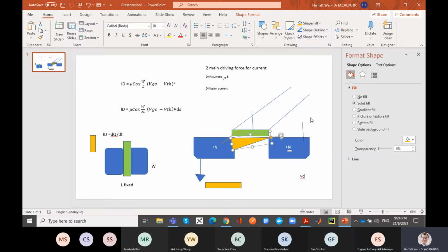Yes. So I start increasing this because I want to keep pulling more and more. But as I increase this, I'm reducing the voltage difference between these two, which means very close to this part here, there's not that much attractive force to pull out electrons, correct? Yeah. But there's still a great electric force here because this is Vg and this is 0 volts. So there's still a large force to pull out the electrons. So I have sort of an imbalanced channel when Vd becomes very large.